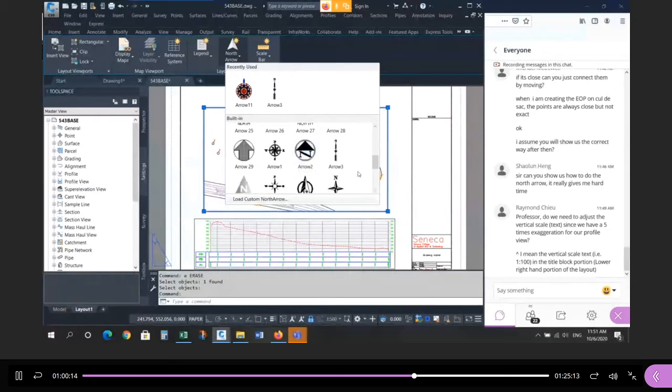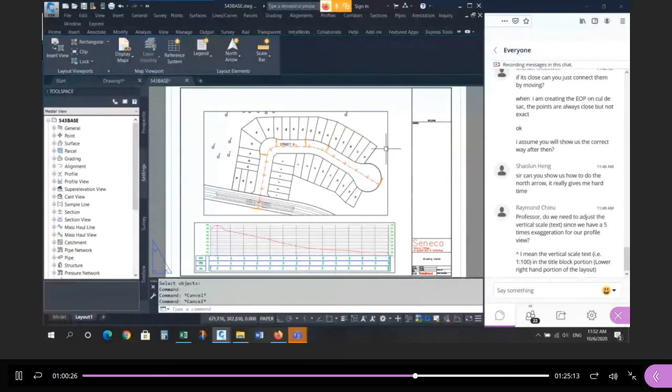Any north arrow of an appropriate size, and again, it's subjective, right? It can't be too big. If it's the first thing that catches your attention, it's too big. If you can't find it, it's too small. There's somewhere in between where it's an optimum size. But the simpler it is, the better. Remember, the focus is the engineering design, not the north arrow. So it shouldn't take away from the focus.